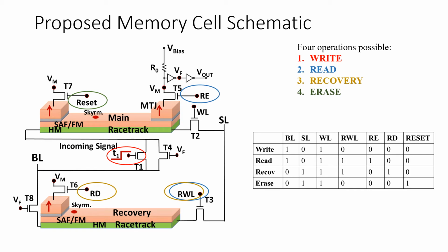Therefore, that complement thing, as I was saying: if you drove it to say W length, and the racetrack is L length, then L minus W is what is going to be read, the equivalent time. So you're going to drive this recovery skyrmion also for the same length, L minus W. That is how you have now encoded that W information, whatever it was, in the recovery racetrack.